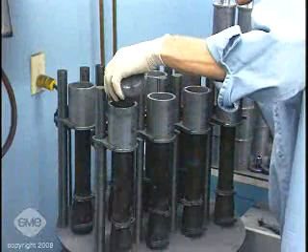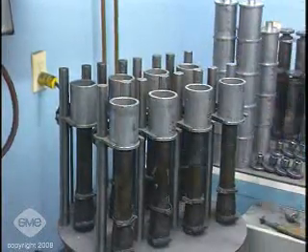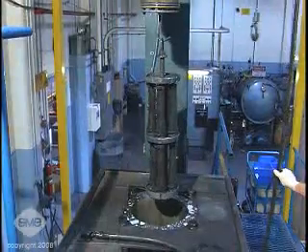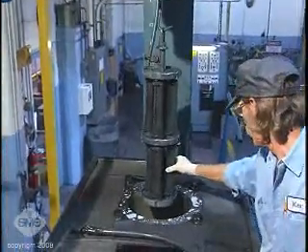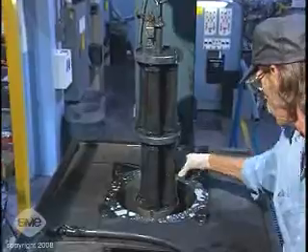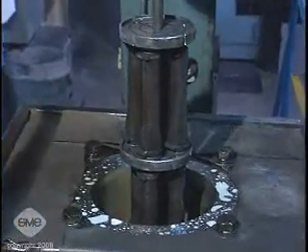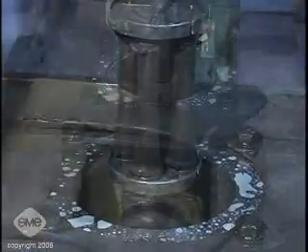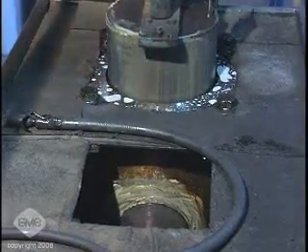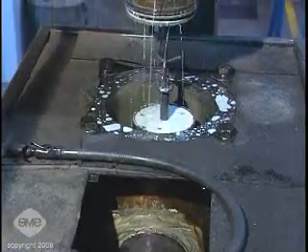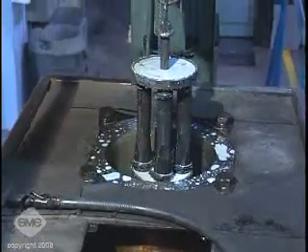The powder is placed in a flexible, pre-shaped elastomeric mold, also called a bag, and consolidated by high-pressure water or oil. Pressures range from 10,000 to 70,000 psi, depending on the powder being processed. Dwell time at full pressure is a few minutes. The molds may be removable or fixed in the press.